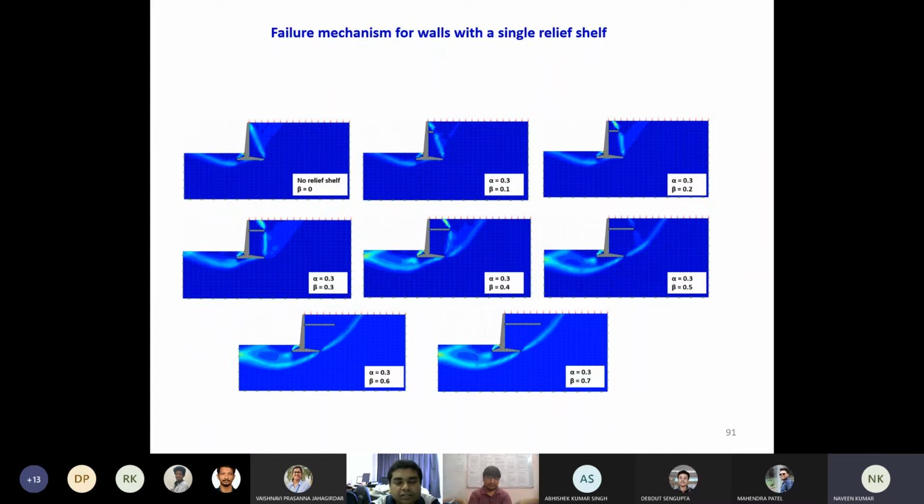Yes, actually, as Dr. Vinay also rightly mentioned, in the book by VNS Murthy and many other books, whenever you look for the design of cantilever retaining walls especially, you will always find that when you configure the dimensions of the wall, the height of the stem is always configured with the condition of the backfill and the slip line which is generated towards the wall.